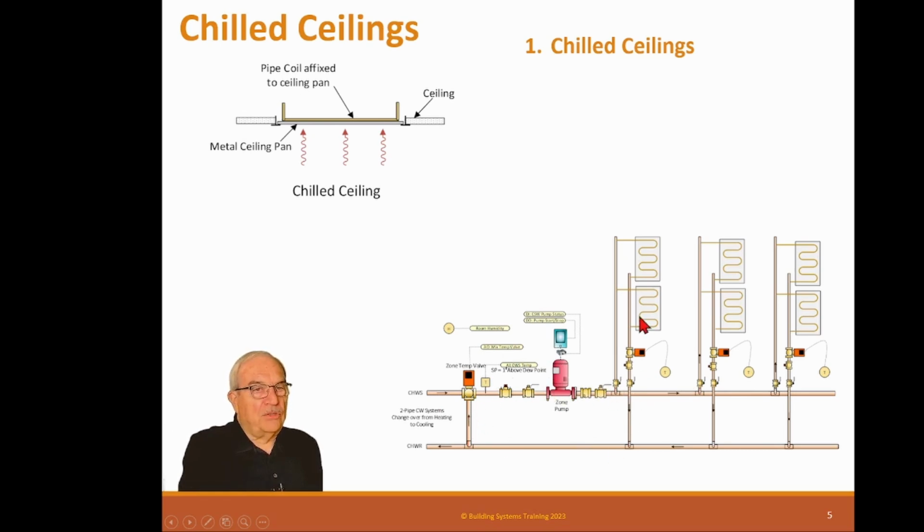And by doing so, these will never sweat. They cannot. There's also a little switch on the back of these. I don't show it in this diagram. It's really simple, just 2 pieces of wires on a felt pad. If it starts sweating, it will sweat on the plenum side faster than the room side because it's warmer, and it will get them wet. The minute they get wet, we shut this valve. So basically we have a switch to never, ever let them sweat.